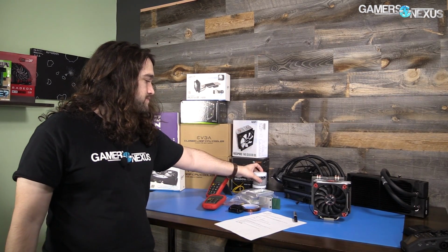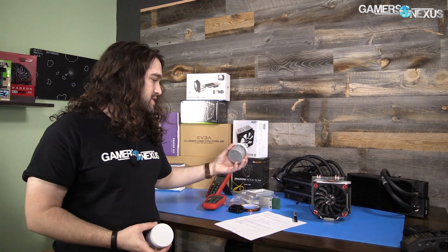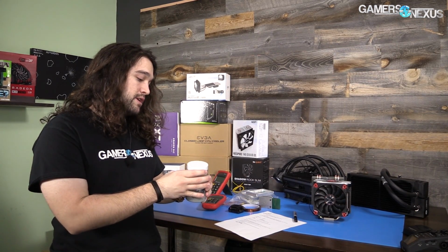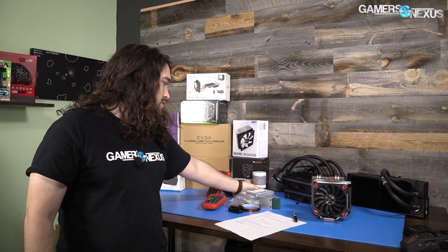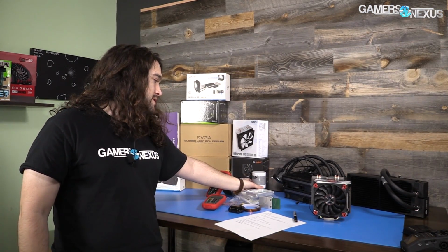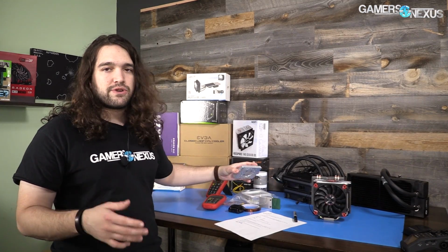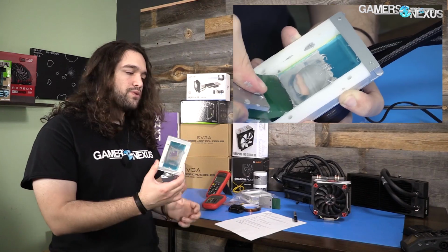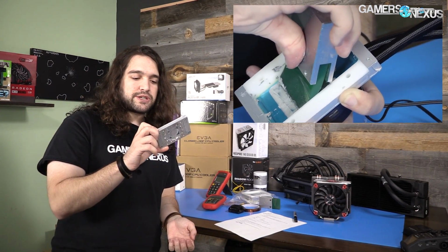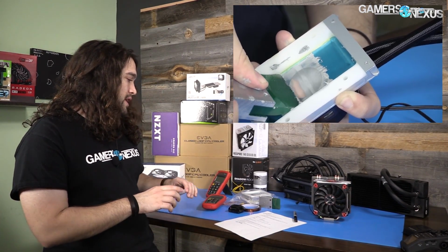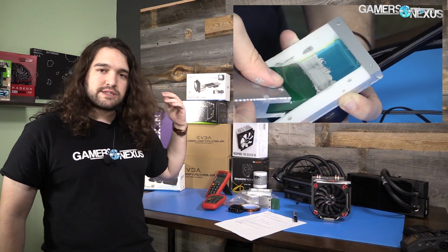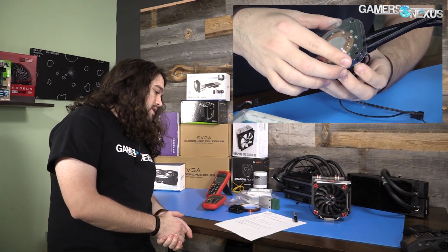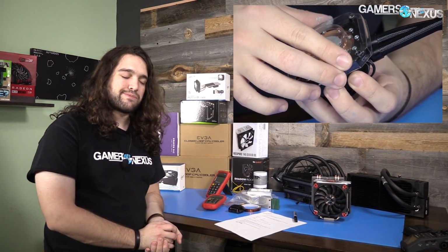Thermal paste. So we have thermal paste from the same batch that we know, same conductivity. All this is getting really, really gritty, not necessarily that important compared to all the rest because the variance is going to be small here, but once you've already done all the other work for all this other stuff, you might as well. So we use, with liquid coolers, thermal paste applicators. This makes sure that, and we've got a video on it, when we apply the thermal compound to any liquid cooler, it's exactly the same. It's equivalent to coming straight out of a factory. And then a fixed application method for your air coolers is important as well.